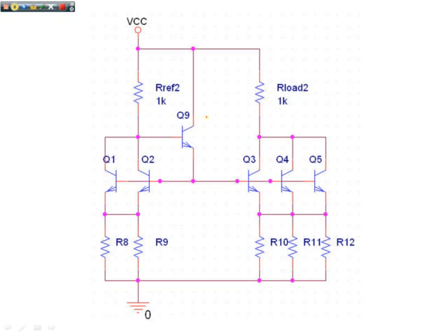Moving on. This circuit at first looks a lot more complex. It isn't. Area equals 2. Area equals 3. On professional CAD tools, we would write that next to our BJT, and all it would do is scale up each of the currents at each of the nodes. In OrCAD we can't do that, so we have to have transistors wired like this. The equations are exactly the same. You define your VE.